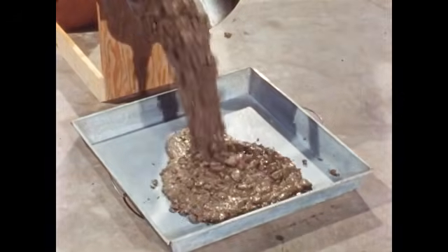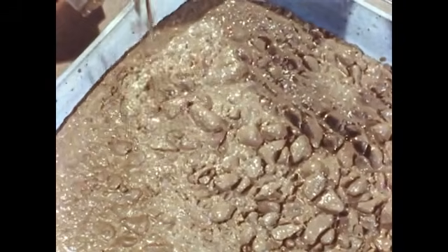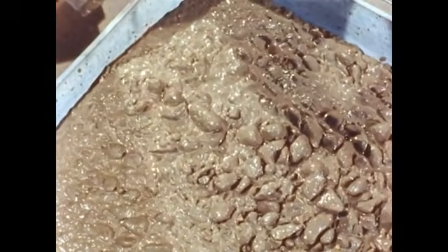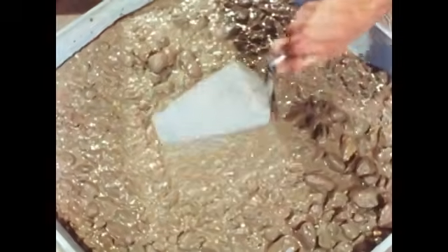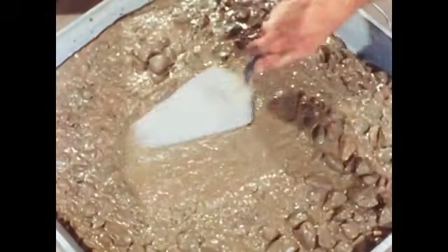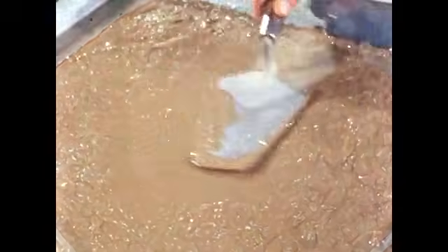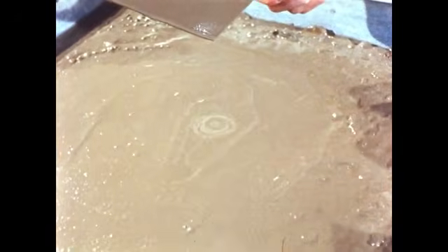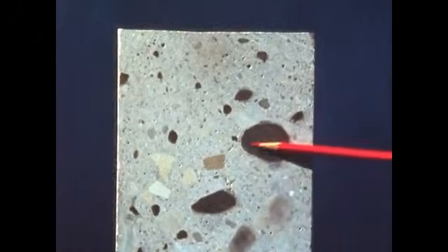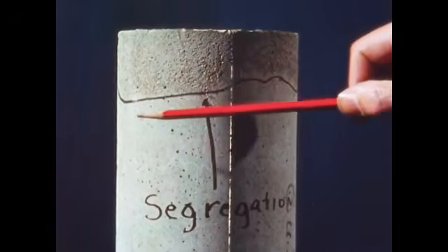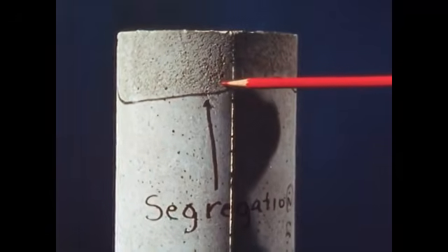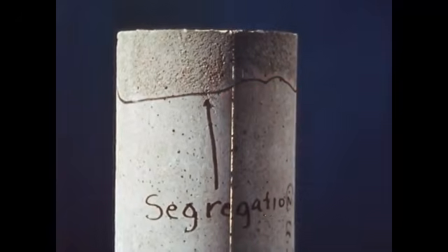Concrete made with too much water will flow easily, but the paste separates from the coarse aggregates, which tend to settle out and collect at the bottom, a condition called segregation. A mix as sloppy as this will result in poor, non-uniform concrete. The bleed water that appears on the surface is caused by the settlement of solids in the mix. As the aggregates settle to the bottom and the water rises to the surface, it leaves channels or pores in the concrete. Worse yet, bleeding increases the water-cement ratio at the surface, weakening that portion of the concrete that takes the most wear and weathering.